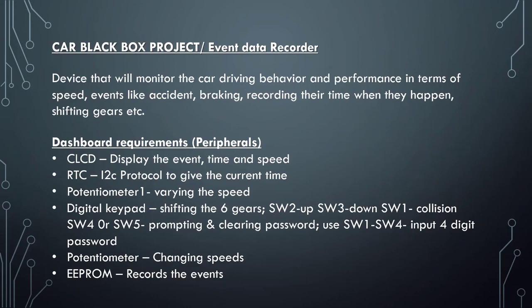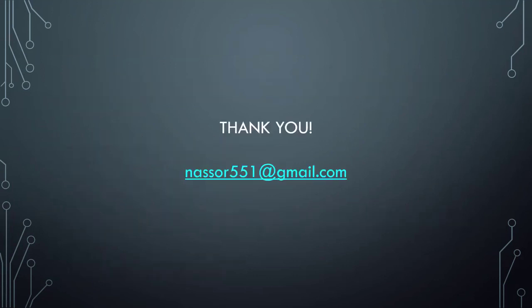For that to happen, we can use switch 1 to switch 4 to input the 4 digits in the order they are supposed to be, so that when a person inputs the wrong password, it gives a delay of almost 15 minutes. Also, as we had seen, we are going to use the EEPROM to record the events. A permanent storage is a storage we can use to record the log events and get them whenever we require. So thank you, and let me share my PICSIM lab.